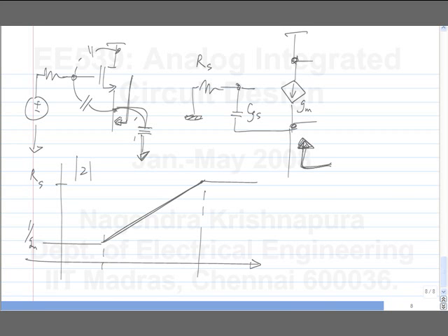But first of all, if you start off with a current, you start with the current here. For the output impedance, what matters is the total current, or at least the current through this part. To establish the output impedance, what you have to establish is that the current lags the voltage here, not necessarily just the voltage across the capacitor or the current through the capacitor. What you are saying is this: the current through Gm lags the current through the capacitor. But it's all in the right direction.